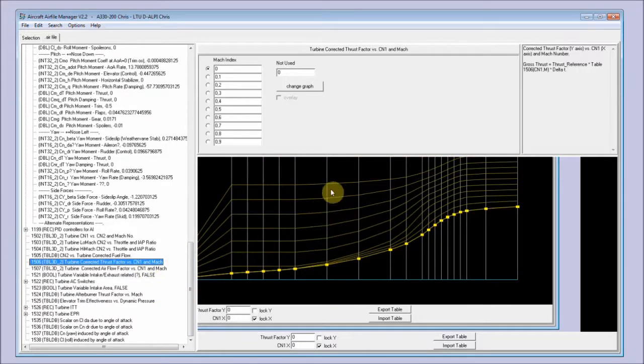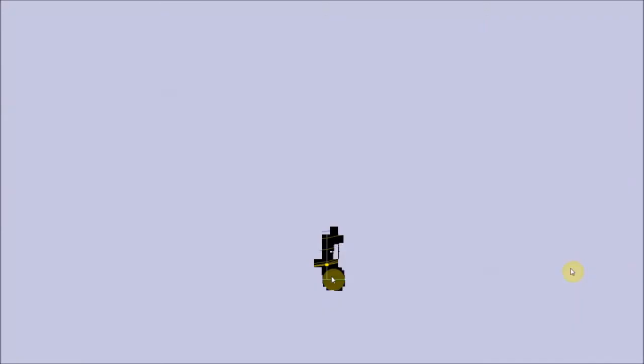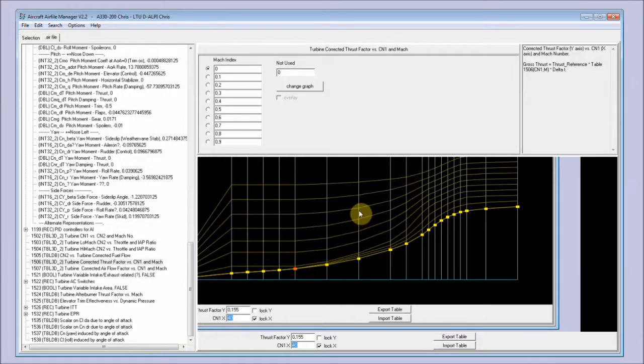the N1 value. So I have to calculate an idle thrust, and idle thrust is in the range around, first assumption, between 20% CN1 and 40% CN1. And now I had to adjust this value here, which affects the force of the engine, so the gross thrust, so that I have a net thrust. So net thrust is equal to gross thrust minus ram drag, which is the ingoing impulse, and I have also steady values here in the first assumption.